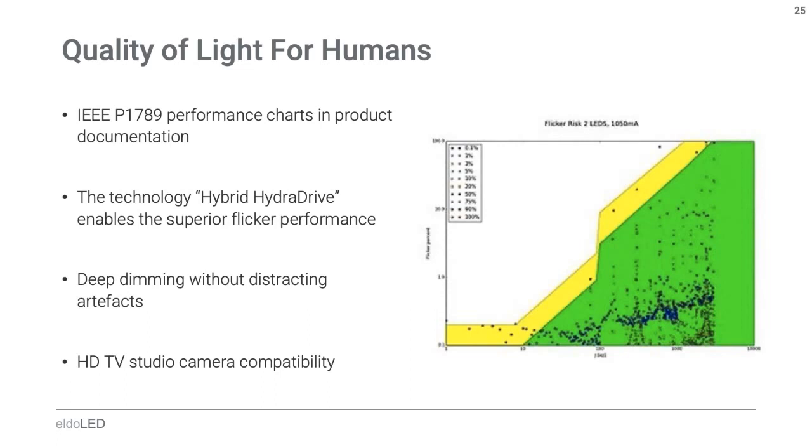And that's not so typical in entertainment and architectural type of lights, because everybody understands in DALI installations that is one of the key requirements. But people think that DMX is flashy in entertainment, but that's not always the case. And that's where the flicker performance of an LED driver comes in handy, next to the fact that most of the times those DMX type of projects also require camera compatibility.